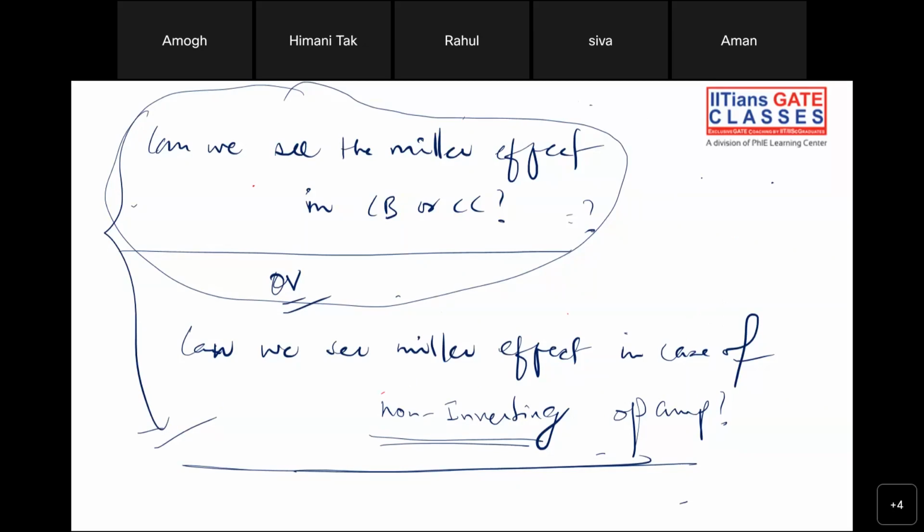So basically in a non-inverting amplifier, the feedback element which we have, if we see from the feedback node from the input side, I can apply Miller's theorem and I can state R by 1 minus A, like the voltage gain across those two points, the output and the input, where the feedback is present.